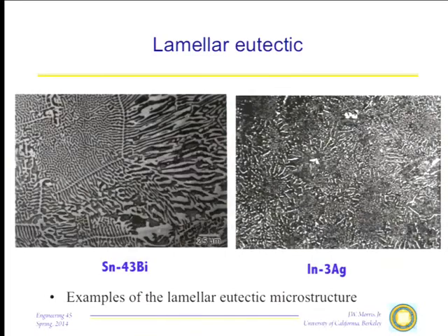You can actually predict that. There's a well-developed theory of the growth of eutectics and the thickness of the plates that come out and so on. And it has to do with, well, there's a thermal issue, because when you solidify, you dump heat. There's a compositional issue, and there are diffusional questions, particularly how fast do these species diffuse through the liquid. You put all those things together, and you can crank and grind, and do a phase field simulation, and get a pretty good model of what's happening in eutectic growth.